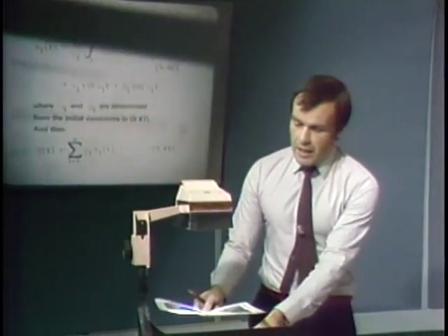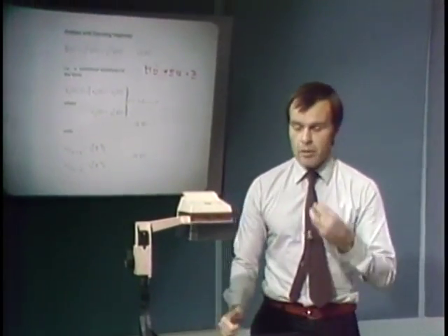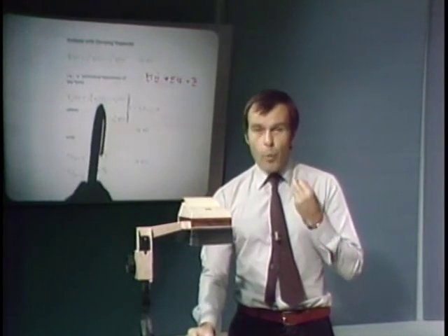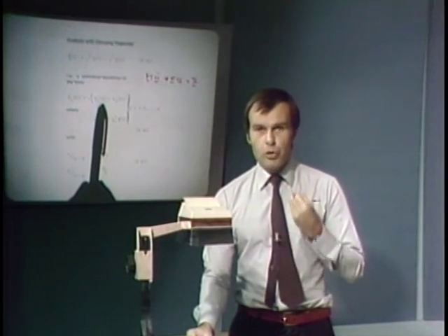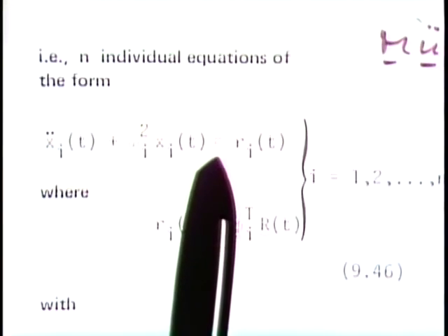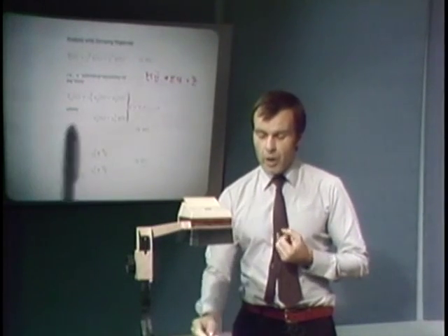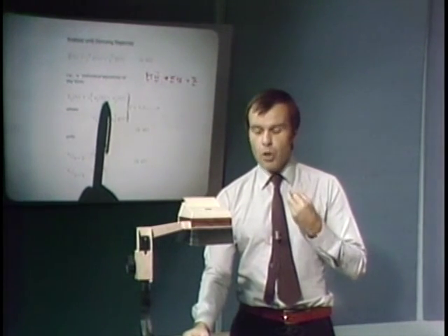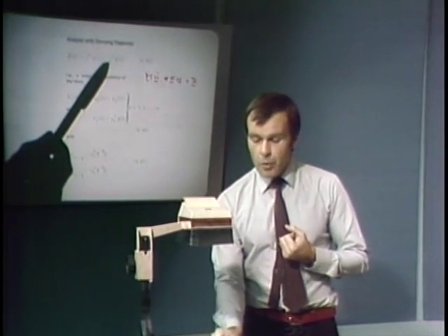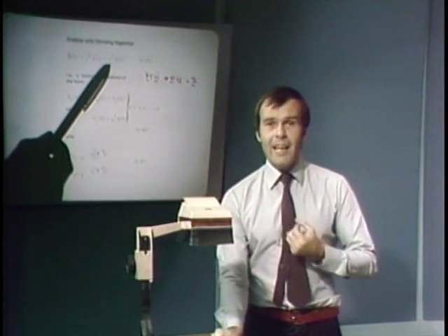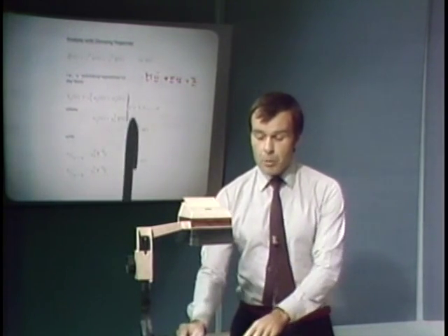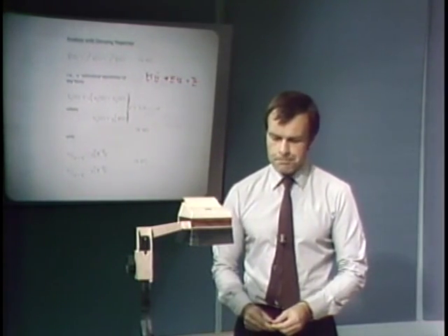Well, the important point that I would now like to get back to and discuss with you for a little while is that we do not need to solve all of these equations in mode superposition analysis. In fact, mode superposition analysis is only effective when we do not need to look at all of these decoupled equations. If we have to solve all decoupled equations, then we would first have to calculate all eigenvalues and eigenvectors, which can be an enormous expense, and then the mode superposition analysis would not be effective.